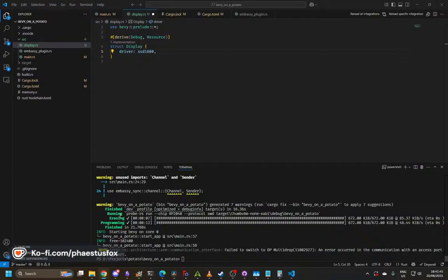I need DC because mine's configured for 4-wire mode or 4-line SPI, and that means I use DC, whereas if I use 3-line, I would need to, well, apparently send an extra bit that then tells it what the pin would be.